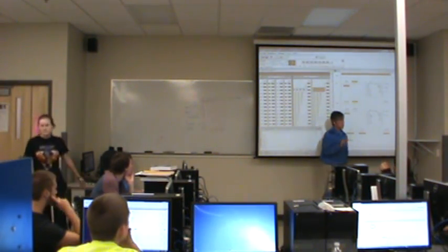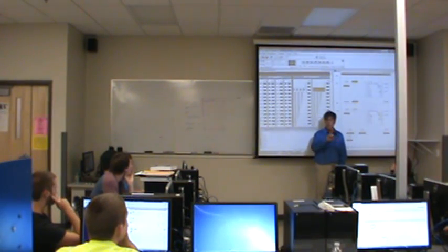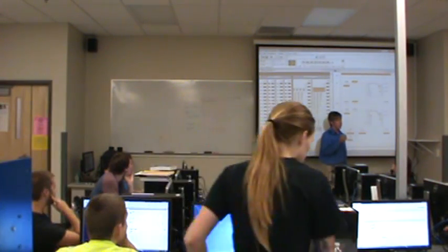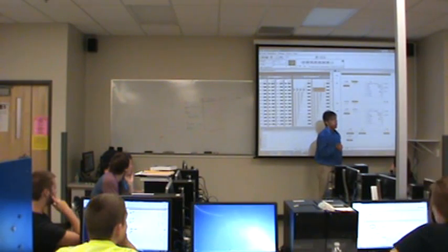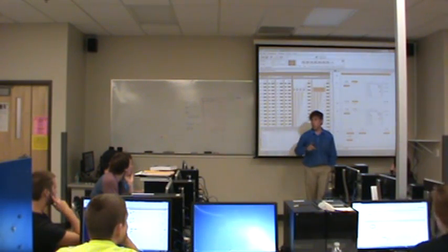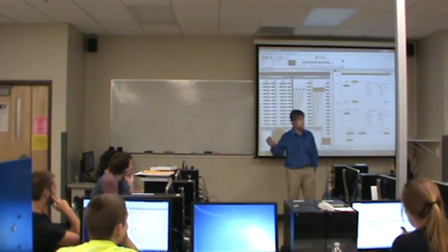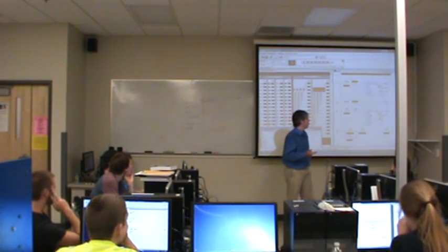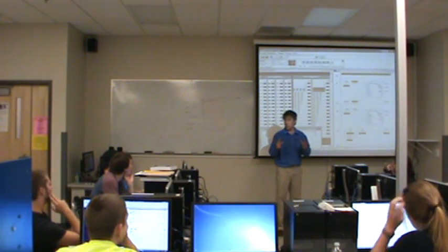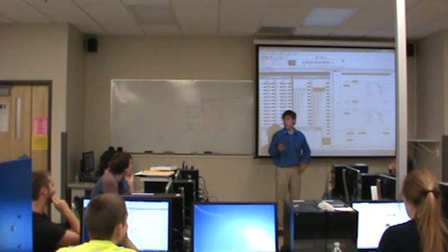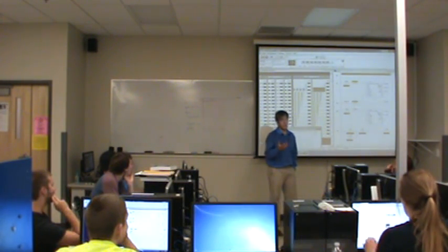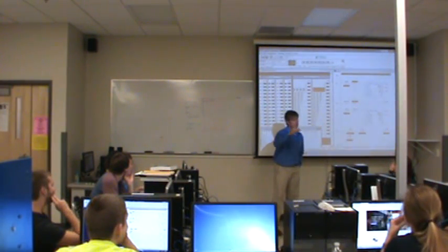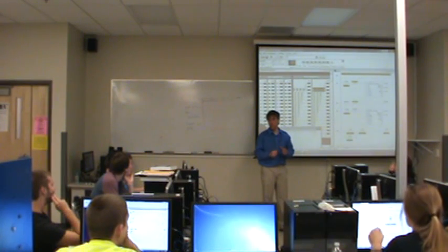I don't want to just look at one input. I may need to look at multiple inputs. I may need to know that there's a bag in place. I need to know that there's enough weight of candy to fill that bag appropriately so that we don't jip our customers. I may need to know that the bag is open and not closed. Okay, so I may have sensors for all this, so there are multiple inputs I have to look at before I go to the next step where I fill the bag with candy.